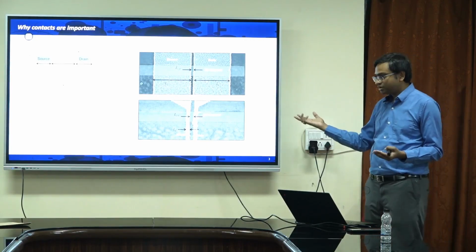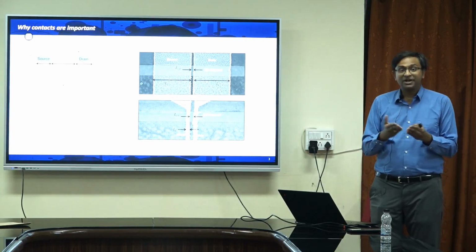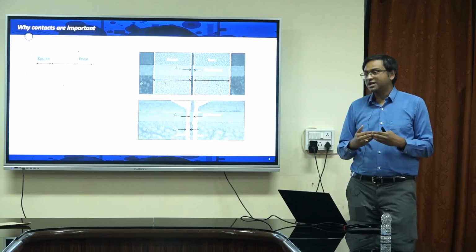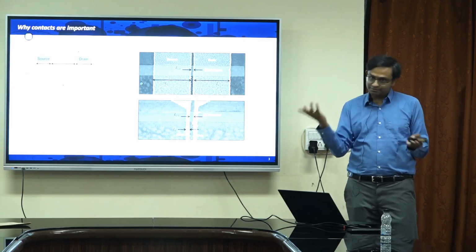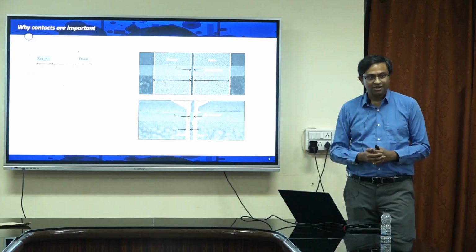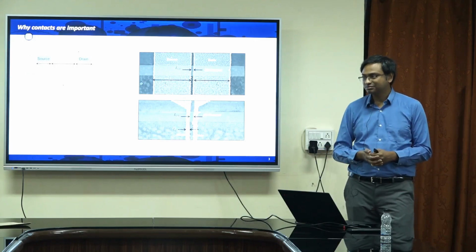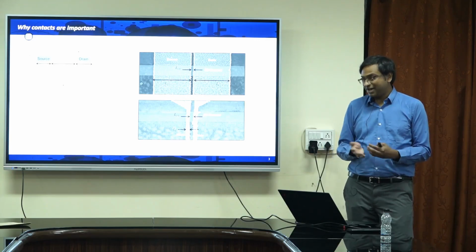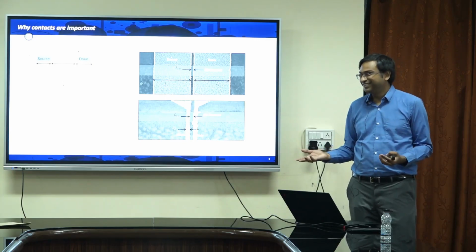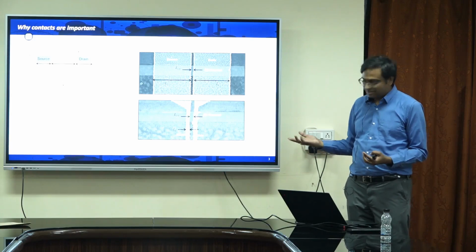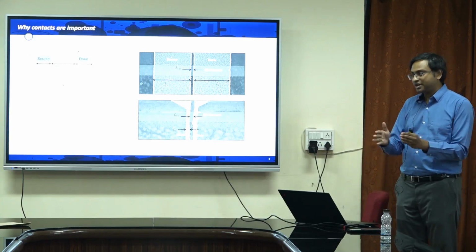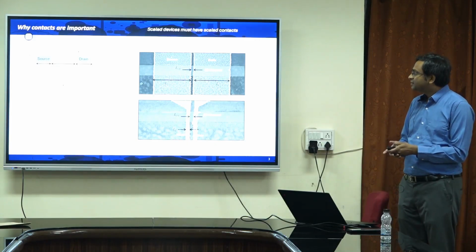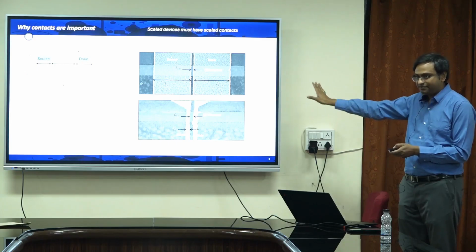And the contact has to be short. So shorter contacts, what do you think? Is it going to give me lower contact resistance or higher contact resistance? We learned that a shorter channel gives me smaller resistance, Ohm's law. Does the same thing apply for the contacts? If it did, then there is no problem, our life is easy. Irrespective of the metal, fundamentally, scaled devices must have scaled contacts, that we established.